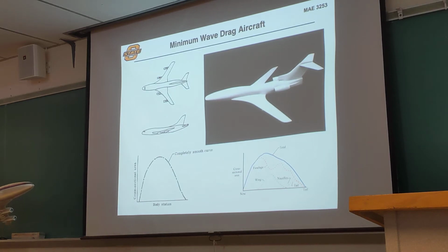We've only seen the advent of winglets on a large scale on airliners within the last decade. But the concept goes all the way back to the 60s and 70s, where again NASA demonstrated that these could have great potential savings in overall drag and improvements in fuel economy by essentially adding these on. And that was Whitcomb as well, who came up with that and demonstrated that concept. That's essentially what's happening with a lot of aircraft now, where they say, here's the aircraft as we purchased it, so we're just slapping winglets on the end like that.